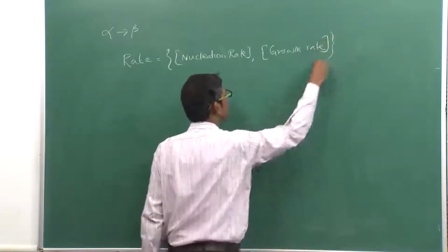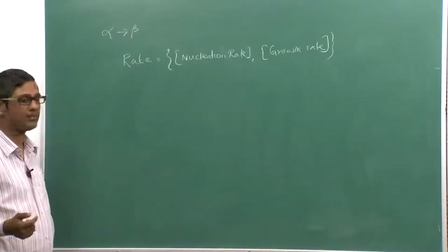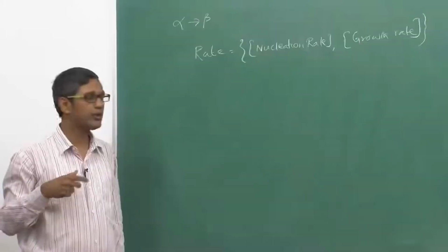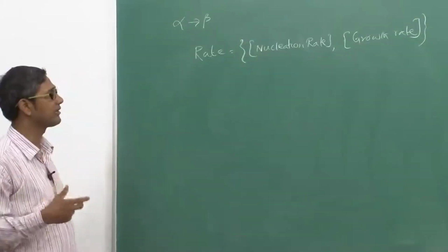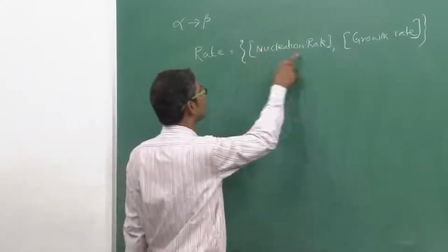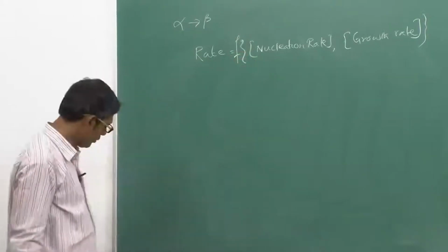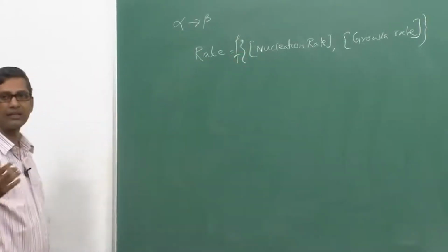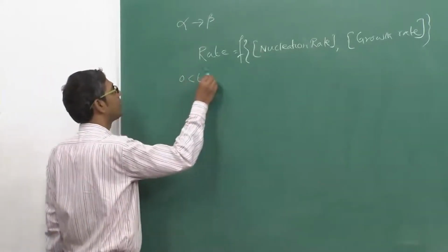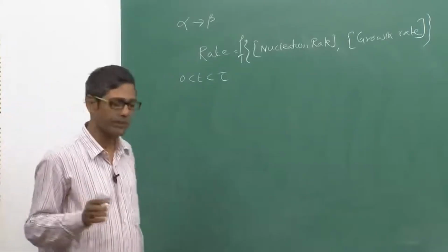As I said, the growth of these strain-free grains is basically dictated by the grain boundary energy. With small grains, you will have a larger grain boundary area, so you have to reduce that, and grains actually start coalescing and growing. So, finally, the rate of the whole process depends on the nucleation rate and the growth rate. Let us consider a very short time scale experiment in the time region of 0 to tau. Tau is basically a very small time scale.